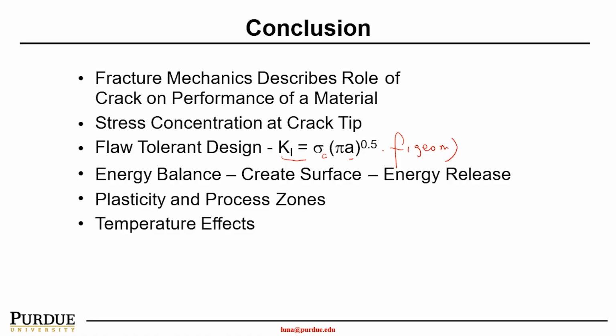And then we talked about the plasticity and the process zone, which is very important for materials such as concrete, a quasi-brittle material with many existing cracks. And then we discussed that fracture toughness is a temperature-dependent material behavior. So as such, it's important to keep that in mind.